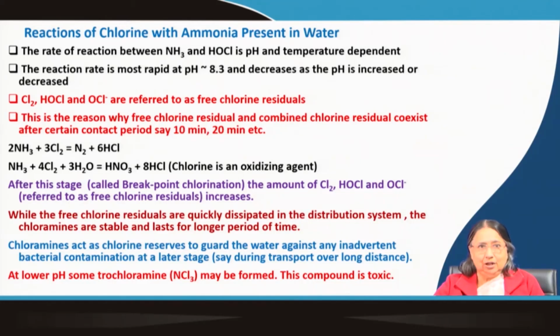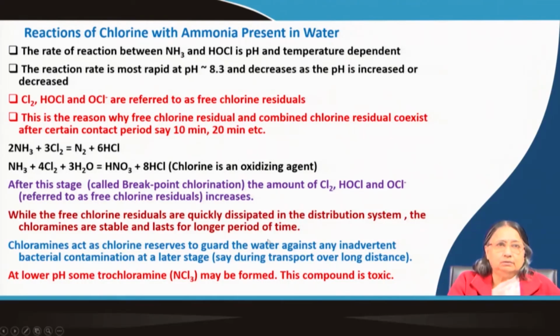This is the advantage of chloramines. That is why sometimes, to protect the water from outside, a little ammonia is also added. So in that sense chloramines are good, they are long lasting and protect over long distance transport.